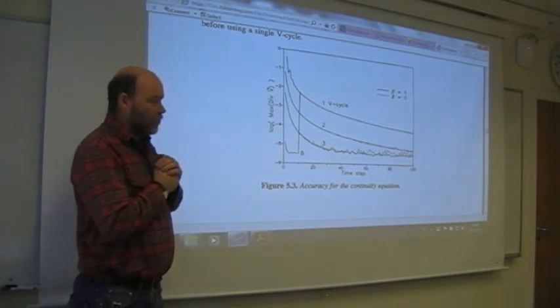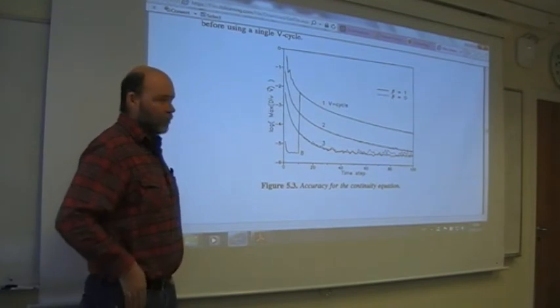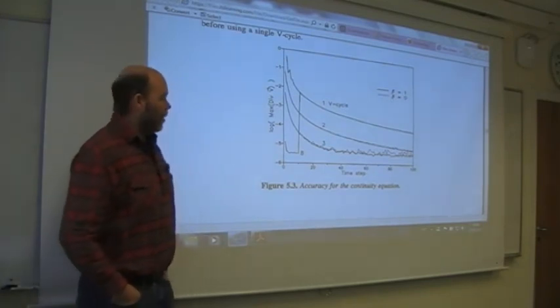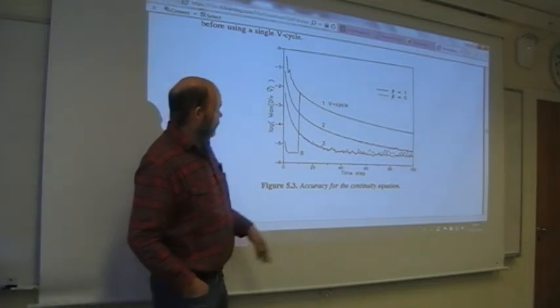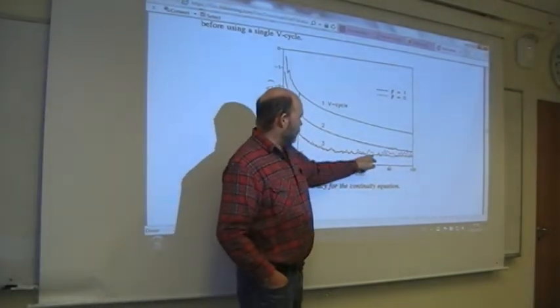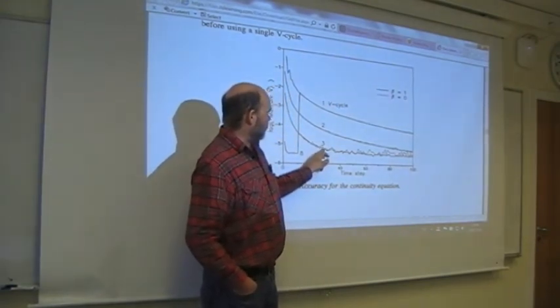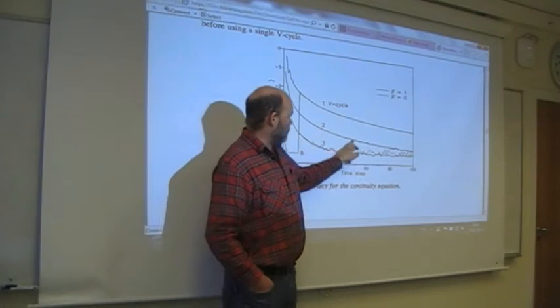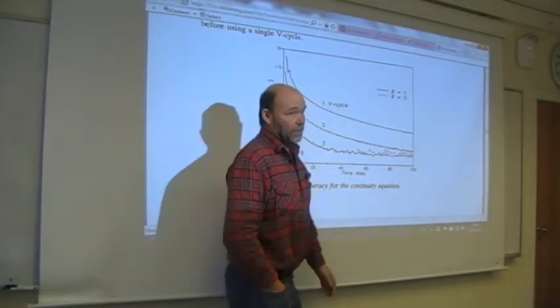But beta equals 0, then you skip the pressure altogether. I mean, this tentative velocity field is going to be wrong anyway. So you have to solve a Poisson equation afterwards. But here you can hardly see that you have any difference. A little bit noise here after 3 recycles, but for the first 2 you hardly see any differences at all. So it really doesn't matter with multigrid.